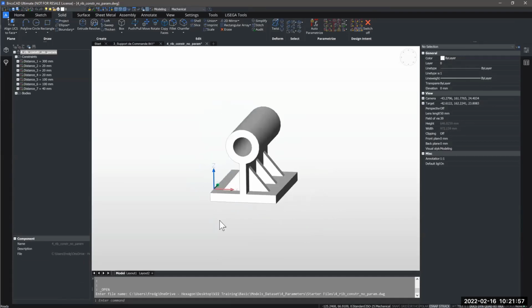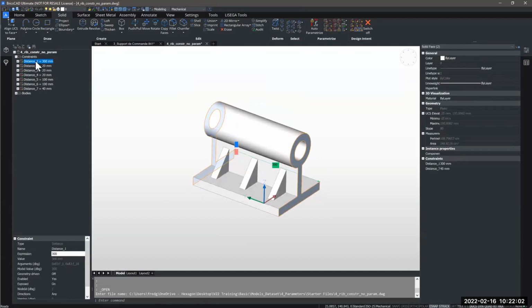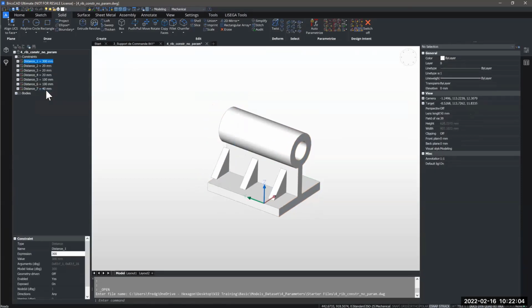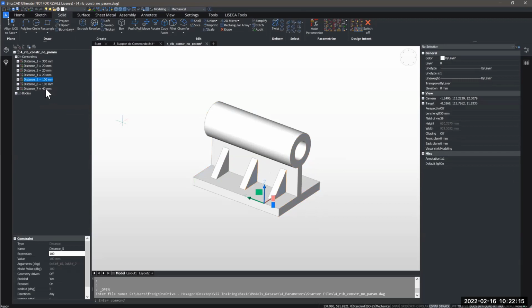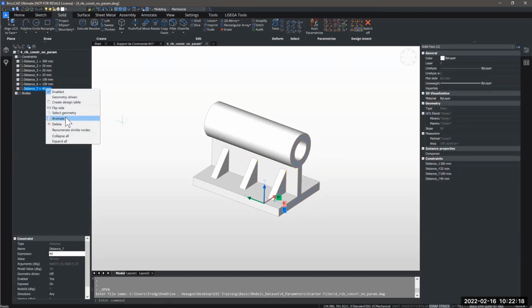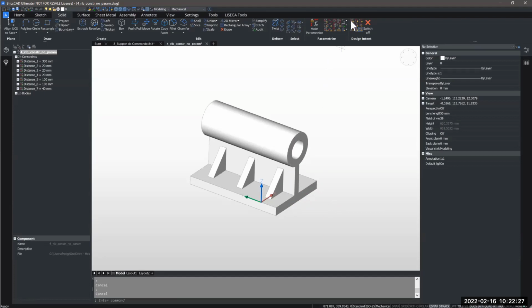Here we have a rib feature. This already has some constraints placed on it. You can see there is a total length applied to it here. You can see there is a value that controls the thickness of the rib, the distance between the ribs, and the distance from the rib to the front face here. However, none of them are working together currently. They are all separate. And we will then fix this and change this.